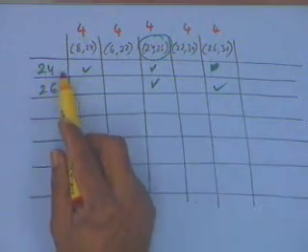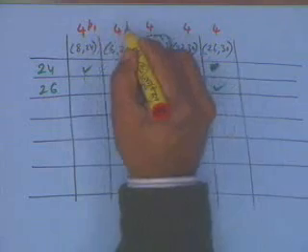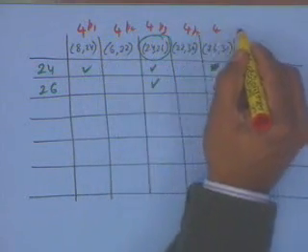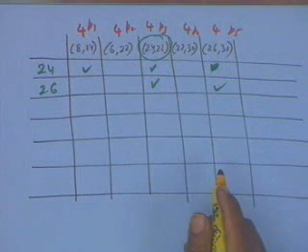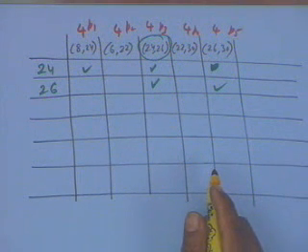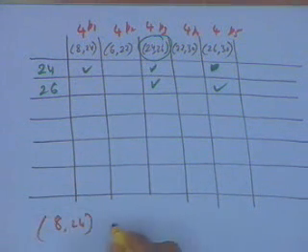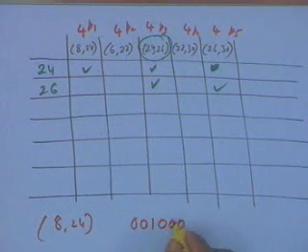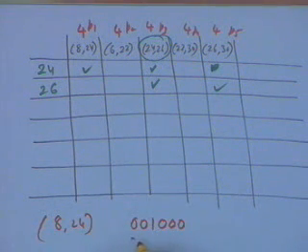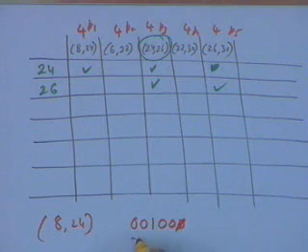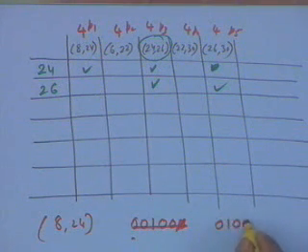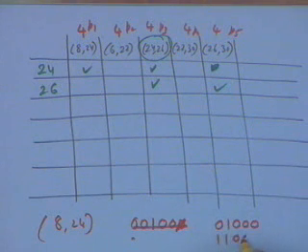So now I call these implicants prime implicants, let us say I call them P1, P2, P3, P4, P5. The cost is the number of literals present. So if it is 8-24, what is 8-24? 8 is 01000 and 24 is 11000.